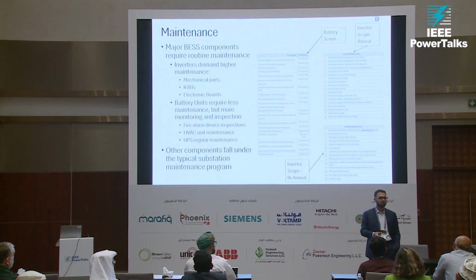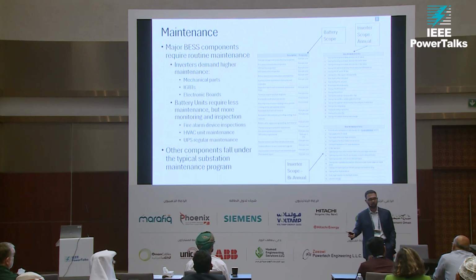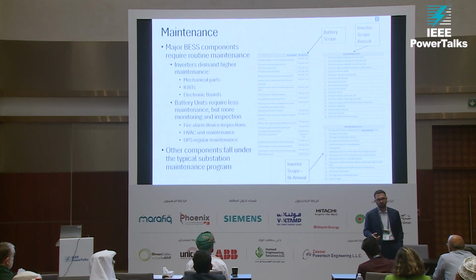We've seen DC augmentation, meaning adding more batteries on the DC bus, so sharing the DC bus. We've seen AC augmentation, adding it on the AC side. We've seen inverter-based augmentation. We've seen co-location augmentation. There are different ways, with a lot of advantages and disadvantages for each. Not going to get to it, but really there's no wrong answer. It depends on the specific project.